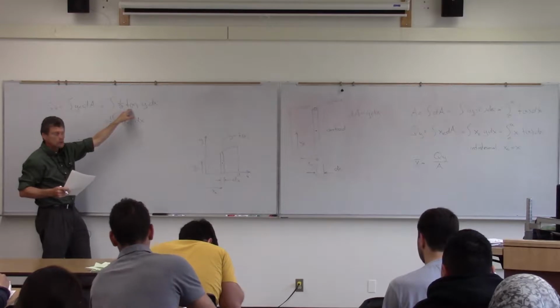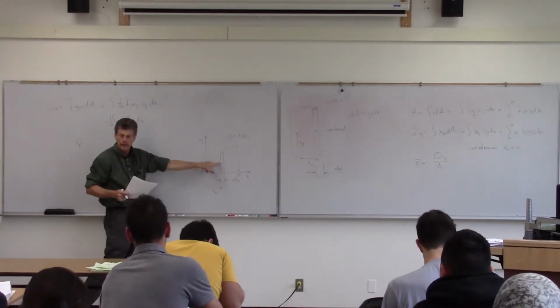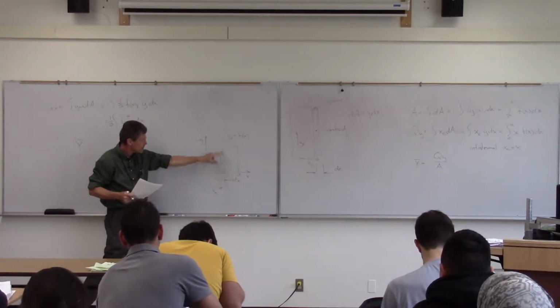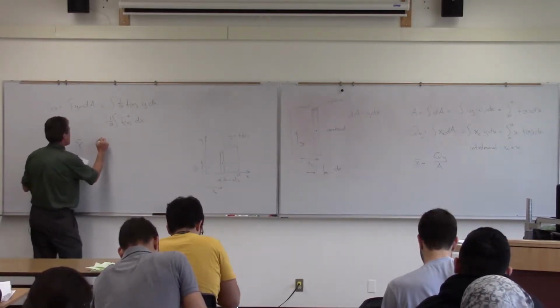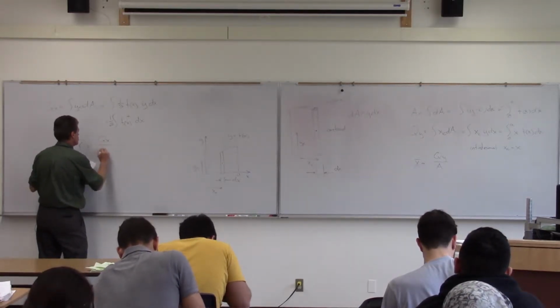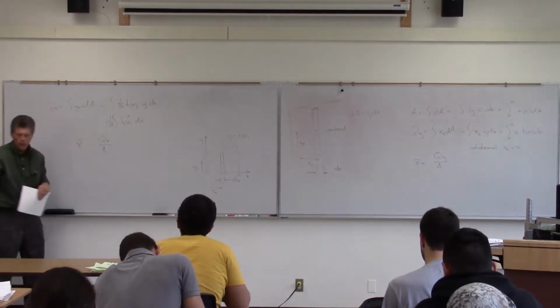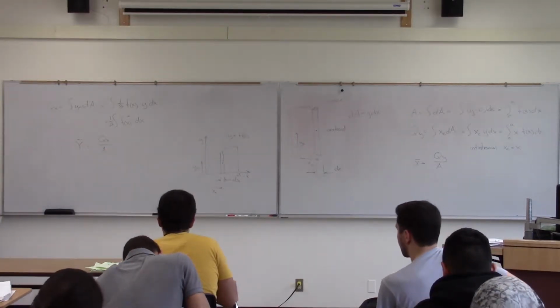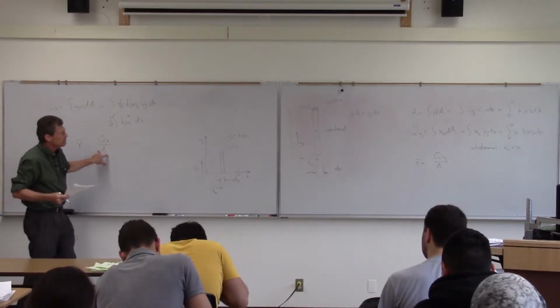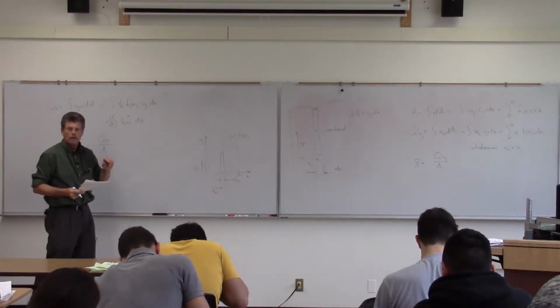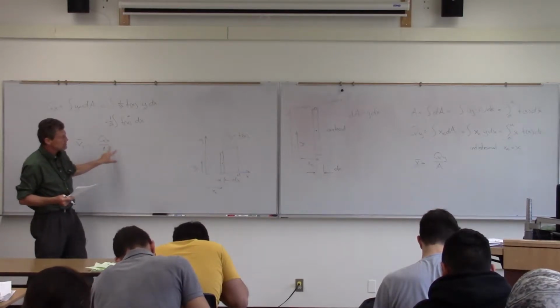And now I've introduced f(x) because I need to get up to that height there of that centroid of that particular vertical strip there. And then going back to what looked familiar, what we were doing a week ago was the same sort of thing. Then take that first moment of area and divide it by that area. And the nice thing is note that I calculated area once. I don't need to calculate it twice. It'll be the same for both.